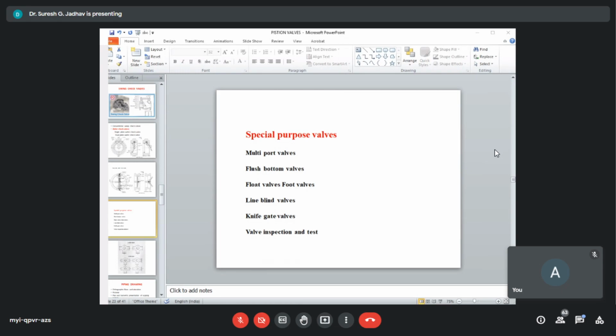The pressure test, unless otherwise specified, shall be carried out on each valve, shell hydrostatic, inclusive of body, bonnet, stuffing box, and cover plates. For this test, discs, wedges, and plugs shall be in the open position and the ball in the half open position.